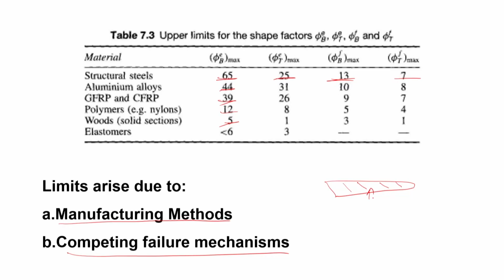The two competing ones will be CFRP and the aluminum. Now, for the aluminum, though you get about 40 times shape factor, the material property index is not as high as the CFRP. So at the end, though for the CFRP the shape factor is slightly lesser than the aluminum, its material property is higher. Now the square root of the product of the two, CFRP becomes higher, and hence it becomes the best choice considering shape factor. Okay. So, that is how shape factor can actually change our decision.